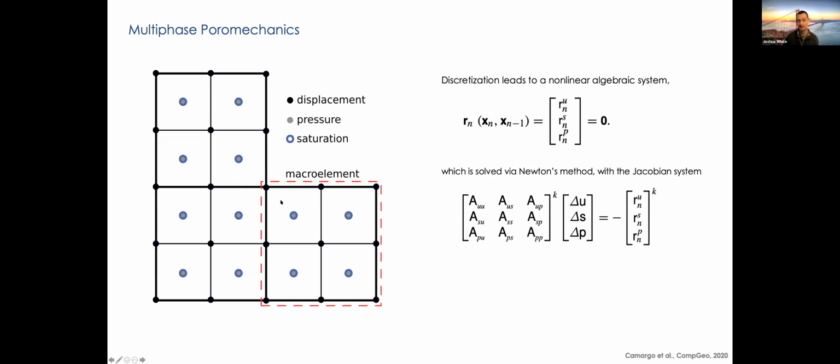One challenge with that one is it's not an intrinsically inf-sup stable discretization. For those of you who are finite element experts, in certain regimes, we can actually run into a stability restriction. And so we usually add an inf-sup stabilization to the system. So we will often use a macro element concept, but there's a variety of ways to stabilize it. Here I've drawn a Cartesian mesh, but there really is no restriction. We typically work on fully unstructured meshes with tets and hexes and wedges and so forth.